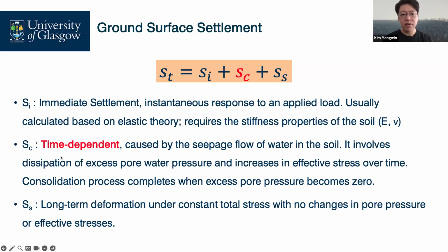Right after the completion of our consolidation process, the excess water pressure becomes zero. Hydrostatic pressure still remains constant. The excess pore pressures due to the applied loading, the additional loads, gradually dissipate over time. At the end, zero.